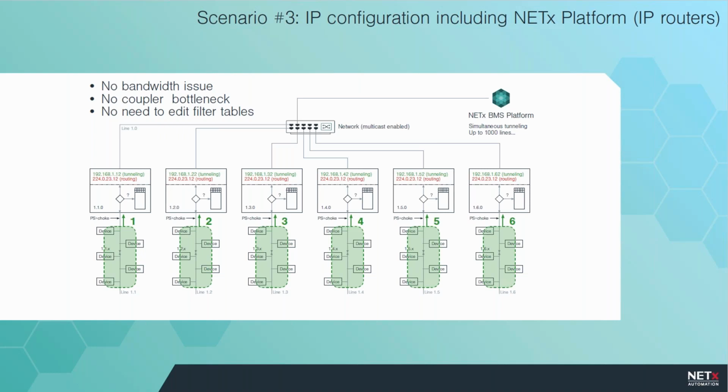Moreover, the most important thing we do in KNX is controlling things: lighting, shutters, alarms, or whatever, and HVAC systems, of course. And these group addresses or data points are mapped to the BMS considering the tunneling IP address of every single line. So it's very interesting, because we can divide the traffic and not upload any traffic to the backbone.